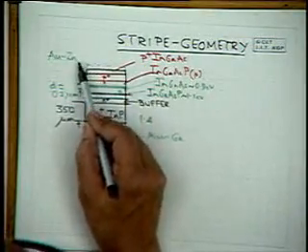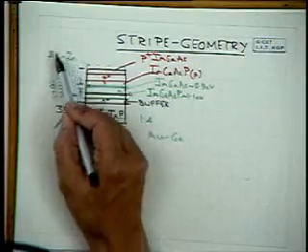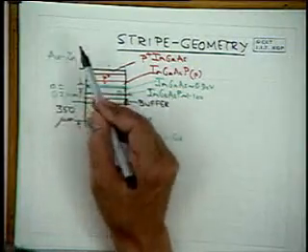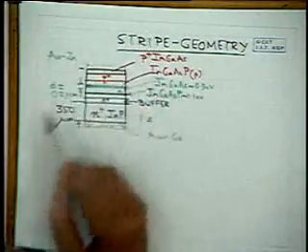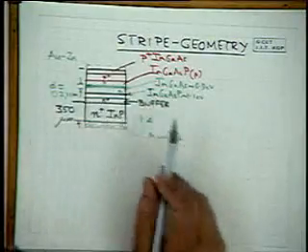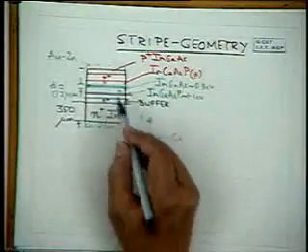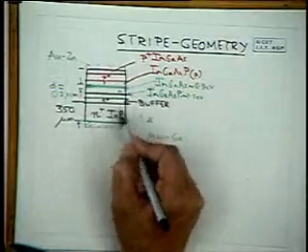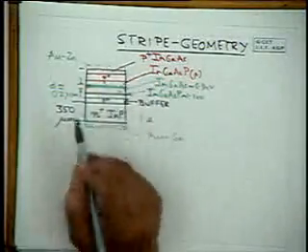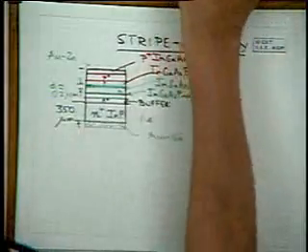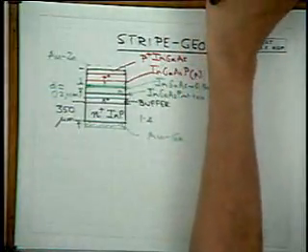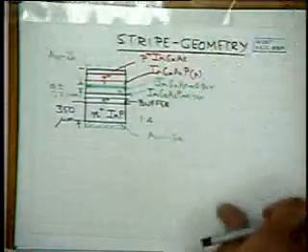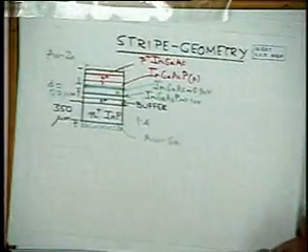Of course, there are other ways you can have multi-layer. You can deposit titanium, palladium, gold, zinc, etc. But I'm sticking to the simplest. Now, if you evaporate over the whole area immediately and cleave and make a device, you will get a broad area. But if you want to make a stripe geometry device, then you go back to the flow sheet.